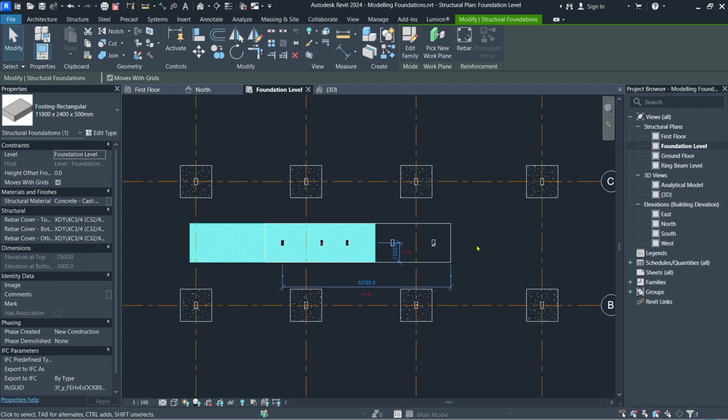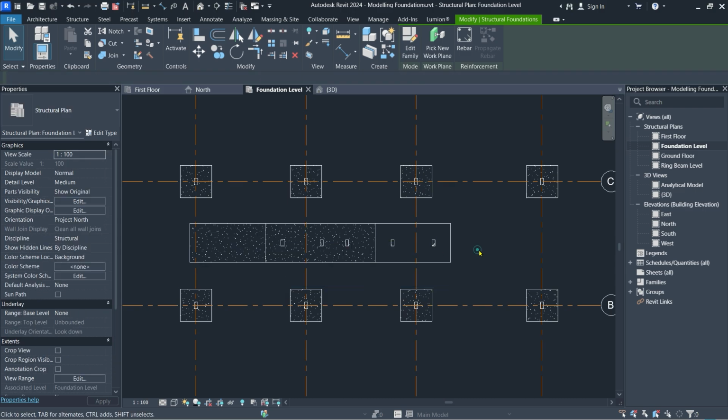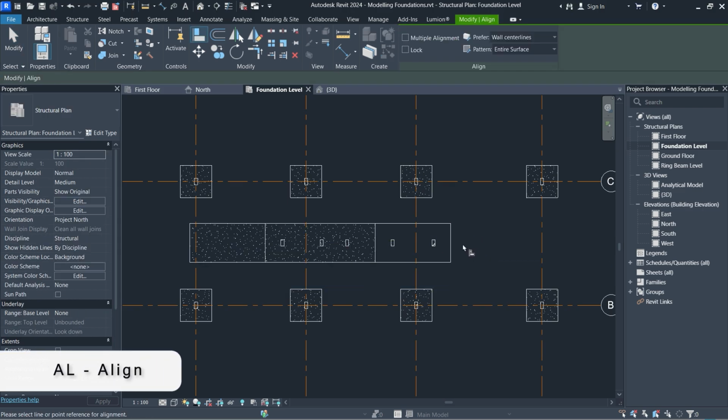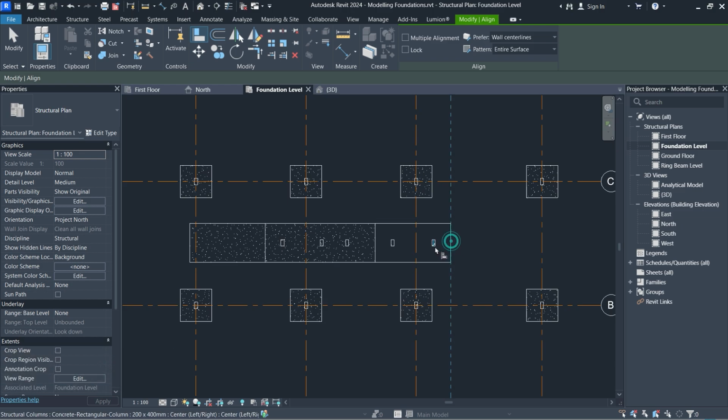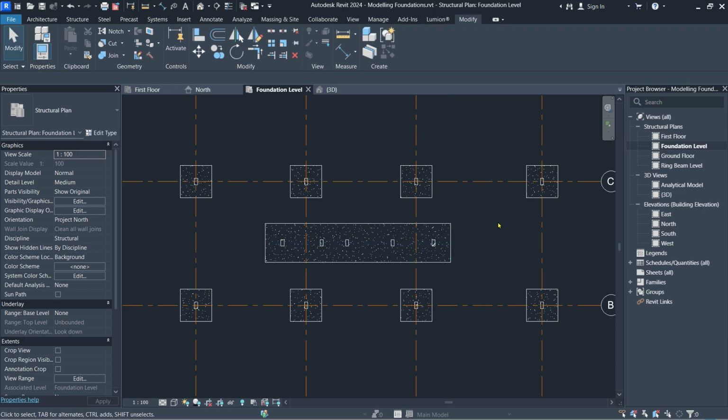Then I'm going to align this edge and this. So I'll say align. Select the reference. This is the reference, not this. The reference, which is the detail line I drew, then the edge of the strip, like so. And you get what you want. Then I can delete the line. Now it's hard to select the line, but it is there.